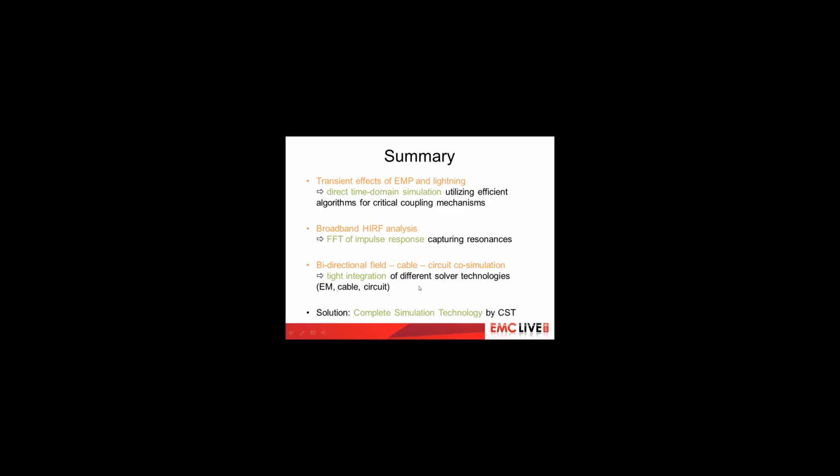Something that I've emphasized in this talk is the importance of bidirectional field cable circuit co-simulation. Tight integration of different solver technologies, or essentially hybrid techniques, allows the physics to be captured accurately, and for the cables, for example, to be really part of the system and affect the field distribution and the current paths. So we believe that this complete simulation technology by CST is ideal for simulating these kinds of lightning, EMP, and more general E3 and EMC problems. So I'd like to stop at that point and see if we have any questions.